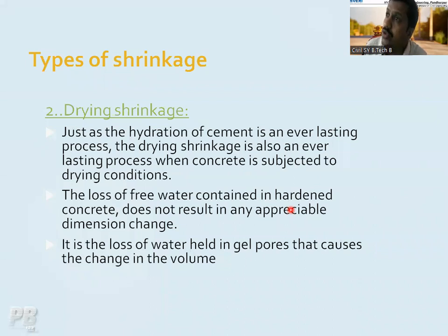So there is a loss of water. There is a loss of water, not from the hardened concrete itself, but from the water which has been held or which has been present in the gel pores.